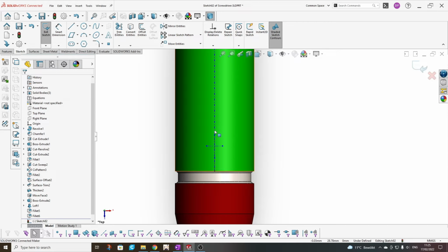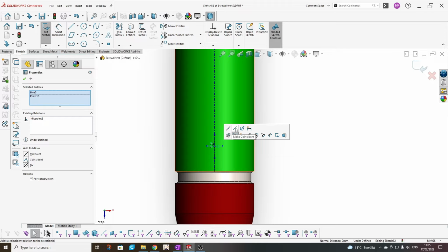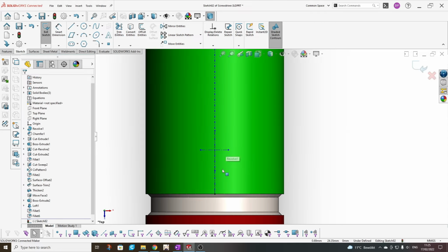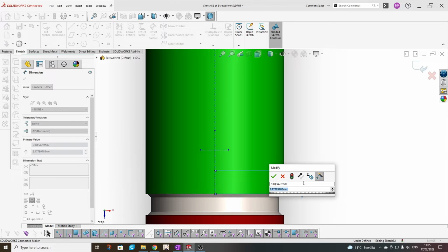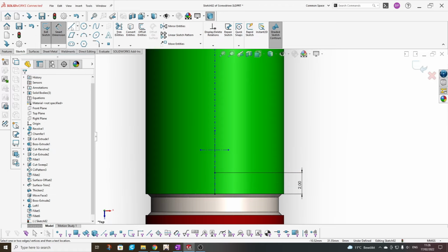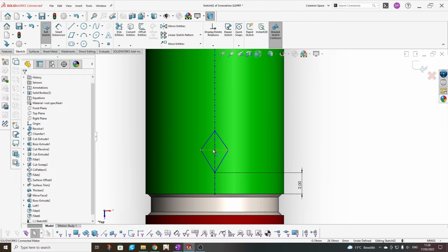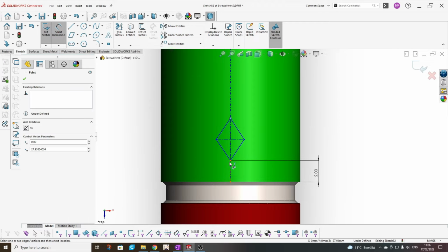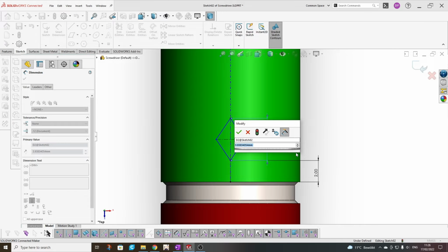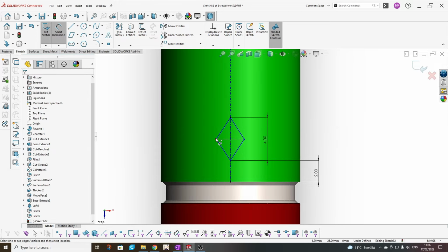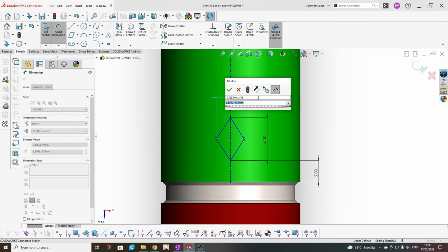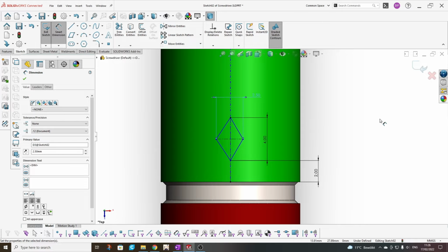As you can see, I model 2 or actually 3 construction lines. First, we'll define where my knurl will start. It will start on 2 millimeters from the end. The other construction lines is to define my knurl size. You can do this in different ways. So what I want is to be 4 millimeter height and 2.5 wide.